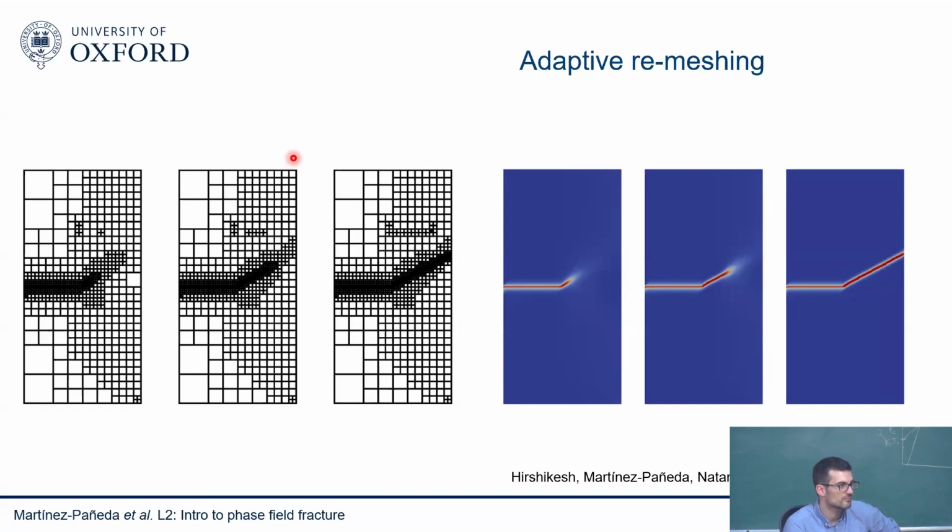So how does it work? Well, you solve another degree of freedom, right? So it's similar to displacement. You will get a value of the phase field in the nodes, and then you interpolate within your element. So similar to the displacement field, any other quantity that you solve. Think of temperature. If you solve for temperature, it is the same as solving an extra equation where temperature is varying non-uniformly in your component. Instead of temperature, it could be phase field.